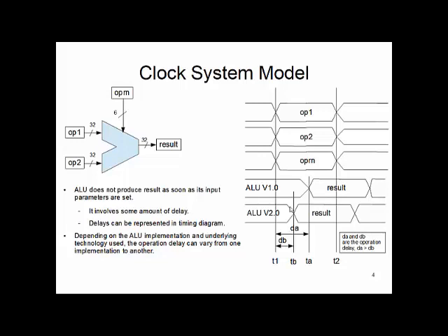There is no human factor inside the computing system which controls when to pick up the result and when not to, by looking at whether the result is available. This is all an electronic system, and it needs something to tell it when to take the result, when the result is done. It cannot just assume it always takes dA or dB amount of time, because the ALU can be operated under different weather conditions, and this delay will vary. So all operation gets messed up, right?